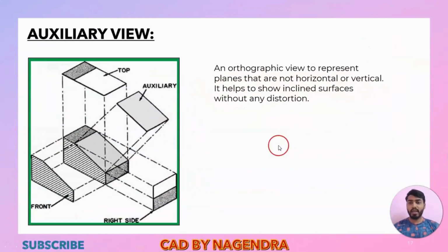Then next we have auxiliary views. What is meant by auxiliary views? Let's say this isometric 3D view is there. We will assume this is the front view. If you look from the front, we get this shape, and if you look from the top, we get these two rectangles, and if you look from the side, we get these two rectangles here. Now let's say we have a different shape on this inclined face.